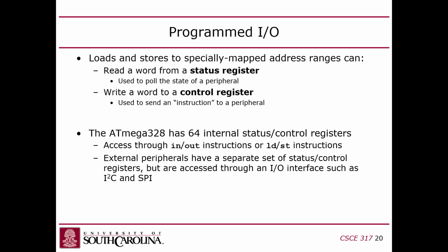But I found in this chip, it's a little confusing because they tend to mix status and control bits together in the same register quite a bit. So you'll find that there's a lot of bit twiddling you have to do, in the sense you might have to extract one bit from a register as an input, but then drive another bit in the same register as an output. It's actually a little awkward sometimes, but it requires that you're looking up the definitions of what each of those bits is for in each one of these registers.